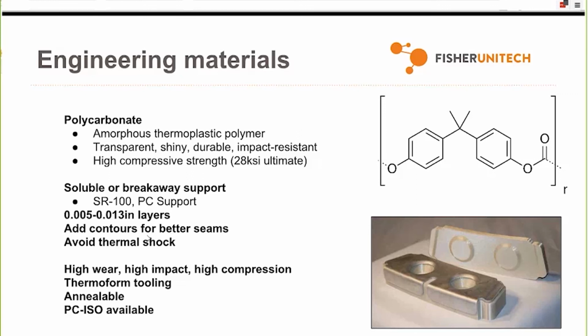And although I personally don't have any direct experience annealing it, I understand that this can dramatically improve the bond strength between those layers because normally the impact strength in the z-axis, which is where parts are normally the weakest, is no better for polycarbonate than it is in ABS or ASA, unless you anneal it. It'll also raise the working temperature, the heat deflection temperatures, and the overall strength of the part. It basically makes it more like sheet polycarbonate, like you might be used to, the same material as DVDs and CDs. Those things are impossible to break.